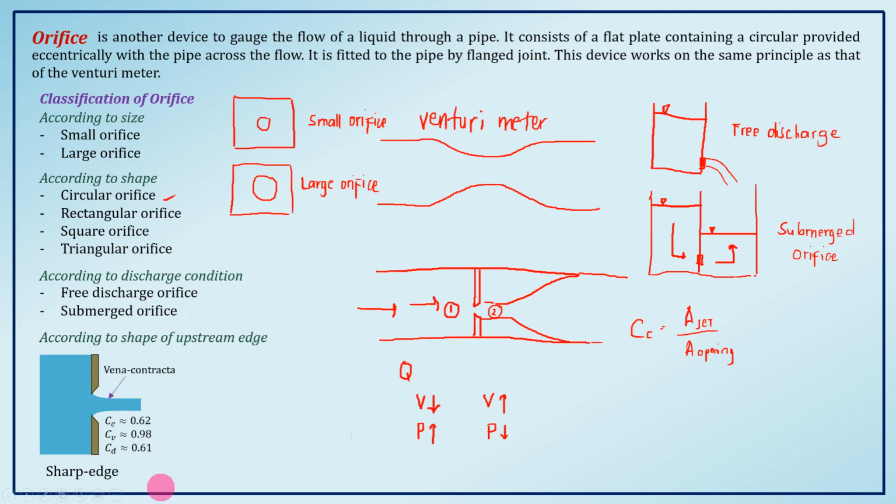So when you see it in the problem, the dimension of the vena contracta is this. That gives us the actual area of our fluid coming out. And this vena contracta is smaller than the area of the orifice or the opening, our hole. The area of the opening is the dimension of our orifice there.